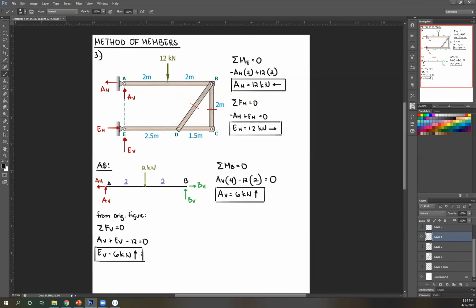So now I've solved for all of the components of our force. Next up, I need to know these, okay? So once again, you might be tempted to use some method of joints here and then method of joints here, right? No, incorrect. Why? Member AB is a 3-force member because it experiences a bending force. Okay? So you can't use method of joints here.